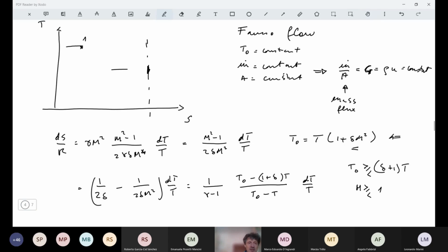And we can find at this point a line like this on this plane. So this is given for a given amount of flow rate, for a given G, and we have a given value of T0 here. And clearly we have a higher difference between the total temperature and the static temperature on the top branch, that would be for Mach number less than 1, and a higher difference for the supersonic branch. In both cases, we can see that we move towards the value of maximum entropy, which occurs here when Mach number is equal to 1.